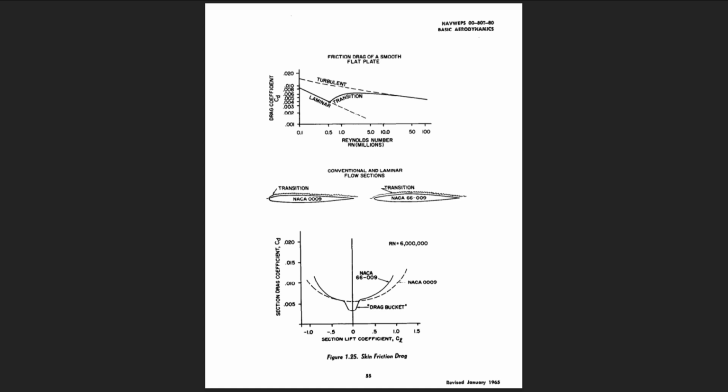In order to obtain low drag sections, the transition from laminar to turbulent must be delayed so that a greater portion of the surface will be influenced by the laminar boundary layer. The conventional, low-speed airfoil shapes are characterized by minimum pressure points very close to the leading edge. Since high local velocities enhance early transition, very little surface is covered by the laminar boundary layer.